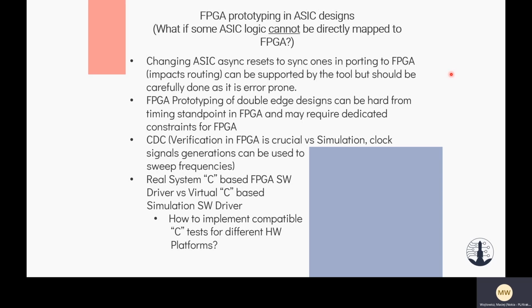The prototyping is also very good for CDC verification because CDC problems are hard to find in simulations, even if we use some dedicated sync flop modules with randomized delay window. And the problem is that even with the most sophisticated cases with randomized clock relationships, we need many hours to simulate milliseconds or even seconds. In FPGA, 1 second is 1 second. So when we use clock signal generators that change frequencies all the time and run those tests for many hours, we will get many hours of different clock relationships, and we need less time to find some possible metastability issues in FPGA verification.